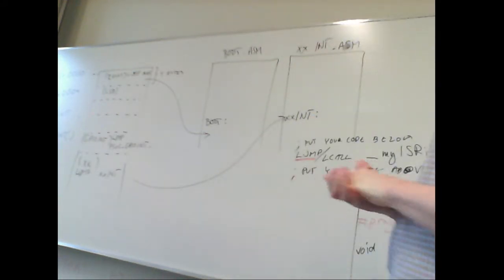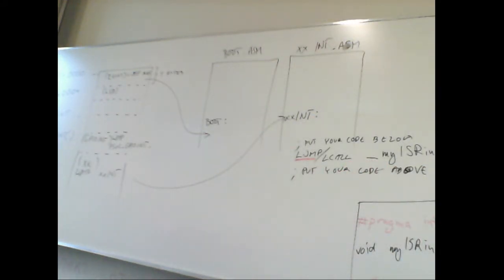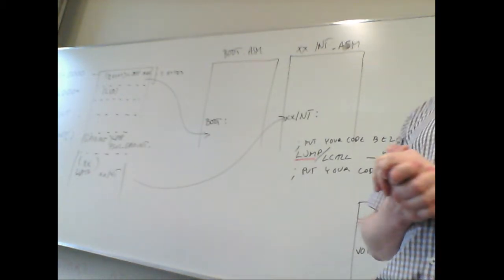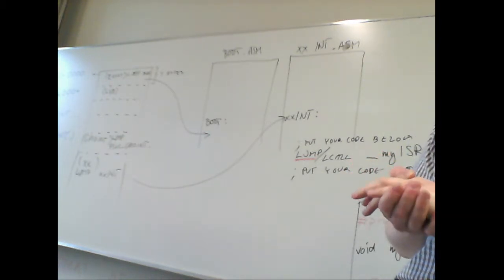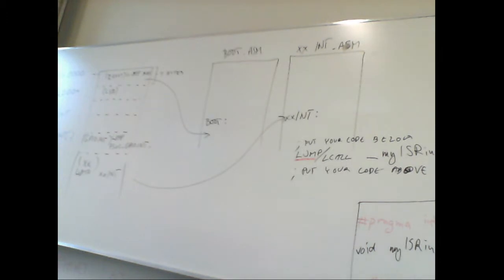There are still a couple of small things on the interrupt actually. Especially, the button press may generate a lot of interrupts unless you do debouncing of that interrupt.